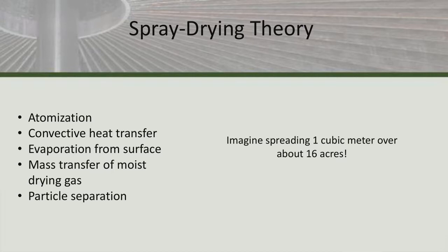Now, everything that we've talked about so far is the easy part of spray drying, and it works every time. But what doesn't always work is that now you have to collect these particles, which are dispersed in a stream of moist and slightly cooled gas. This is accomplished via filters and cyclones and scrubbers, or a number of different types of technology. But this really does constitute the challenge in spray drying, and most of the development work is focused on this step, making sure that the powder conveys properly through the system and can be recovered.